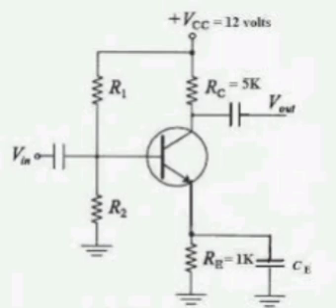So G11 equals I1 by V1 equals S plus 2 by S square plus 3S plus 1. G21 equals V2 by V1 with I2 equal to 0. VAB equals V1 into 1 by S, ZAB equals S by S plus 1. V2 equals VAB into 1 by S plus 1 plus S by S plus 1. V2 like that we will calculate. V2 by I2 equals Z equals S by S plus 1 plus S parallel 1. Like that we calculate all the G parameters.